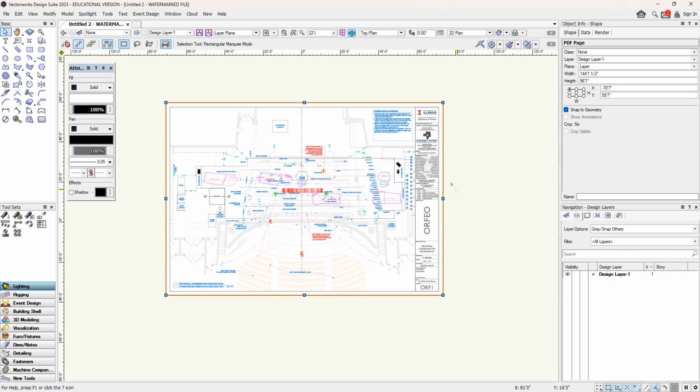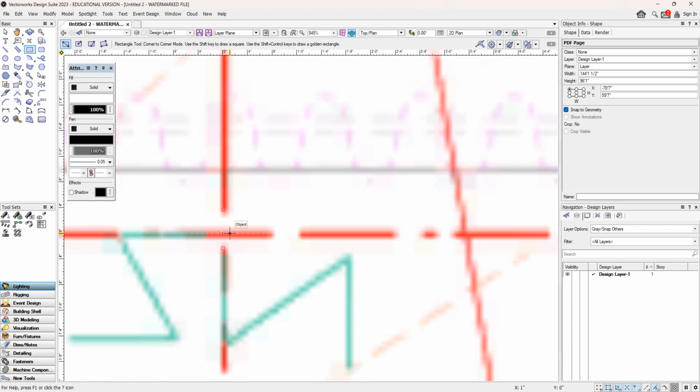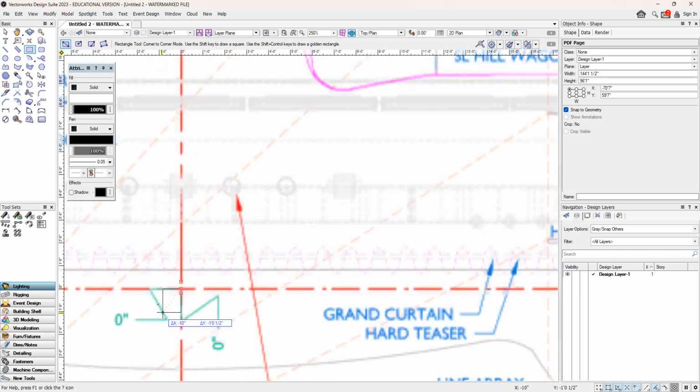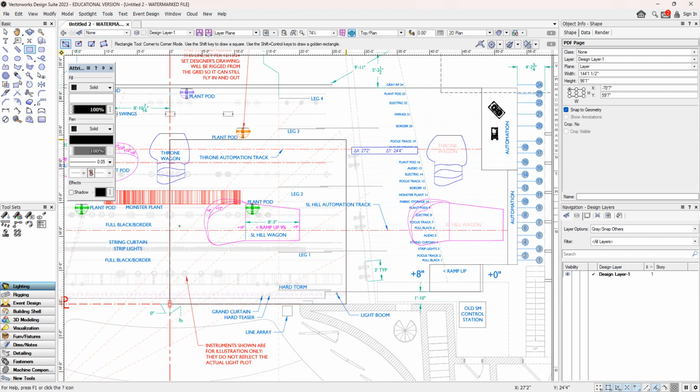Okay, so our drawing is imported, it's scaled correctly, and 0 is where we want it to be. Now we can take measurements, right? We can do this very similarly in AutoCAD. I could use my tape measure tool, but I can also just grab my regular 2D basic rectangle tool, find that 0, 0, click there, and now as I draw this rectangle, you'll see that it displays a little bit differently. I'm seeing a little tooltip there that says delta X and delta Y.